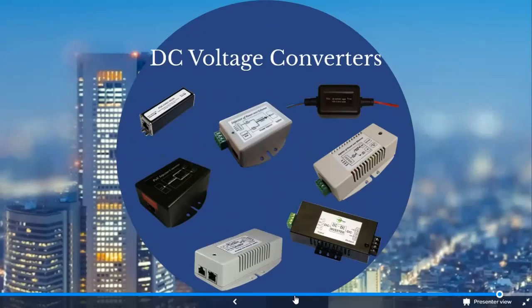Different PoE converters as well. Let's say you have a 48 volt switch and you need one port at 24 volts. You can use the PoE converter 4824, which converts 48 volt down to 24 at gigabit.